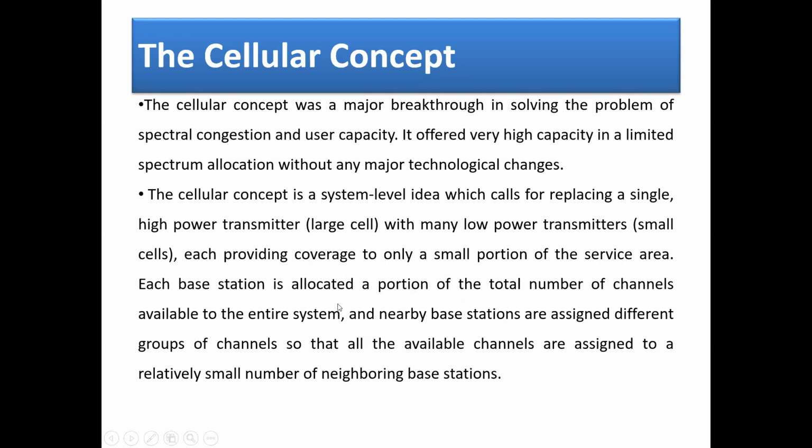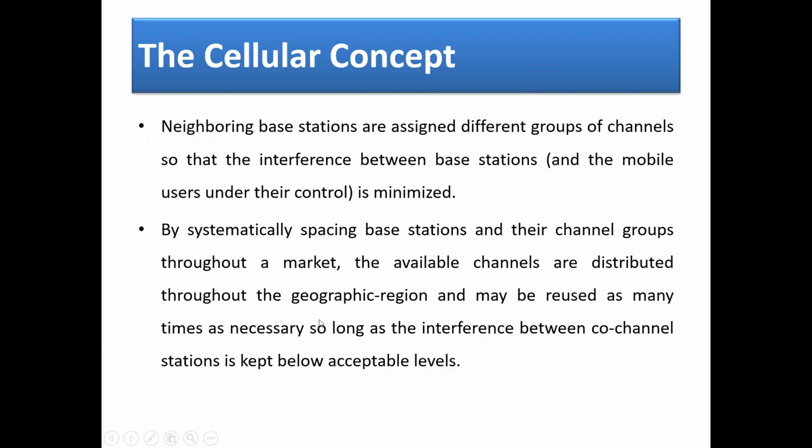Each base station is allocated a portion of the total number of channels available to the entire system, and nearby base stations are assigned different groups of channels so that all available channels are assigned to the relatively small number of neighboring base stations. Of course, I'm going to illustrate this step by step on the whiteboard, but let me complete these 2 points again, and then we are going to go to the whiteboard.